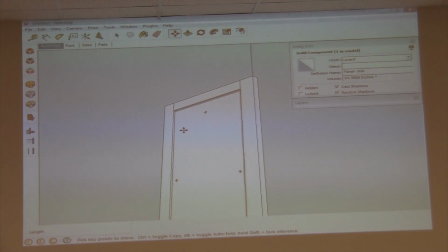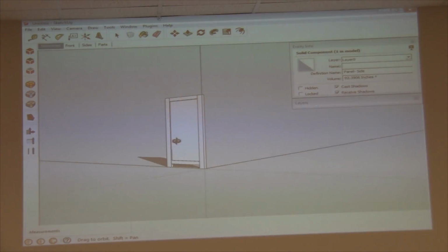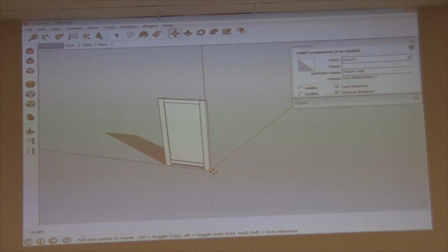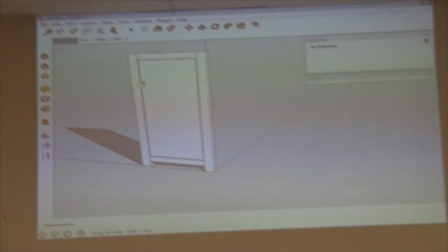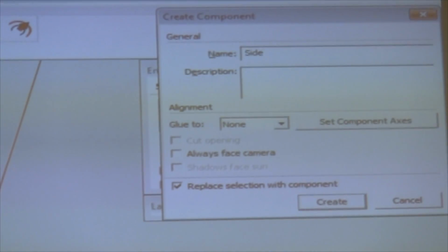If you make one of those legs disappear, and there's a way to do that, hide it is what they call it, you can check the fit, and then unhide it back. Well, with this one, you could also go to the x-ray and look at how it's sitting inside the board. But essentially at this point we now have another component made up of components. So I'm going to select all of these and call this a component. I'm going to call it side left.